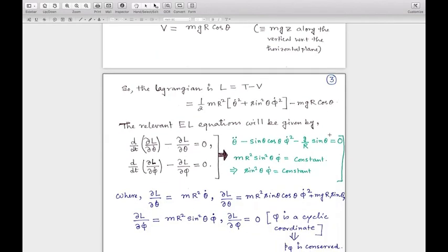So in this Lagrange's expression, you have two types of generalized velocities, but only one type of generalized coordinate. The generalized coordinate which is absent in the Lagrange's expression, although it is a varying quantity, not fixed, but does not appear explicitly in the Lagrange's expression, is known as a cyclic coordinate. I will discuss it later. And that will have some interesting property.